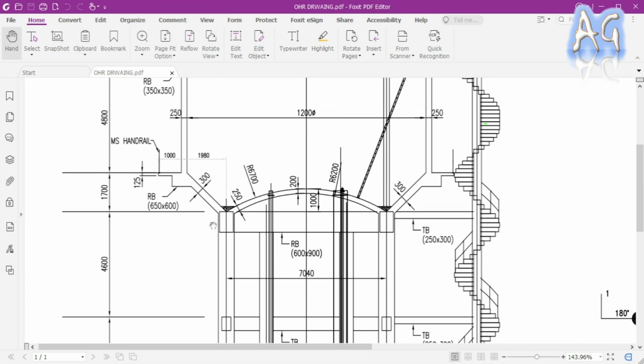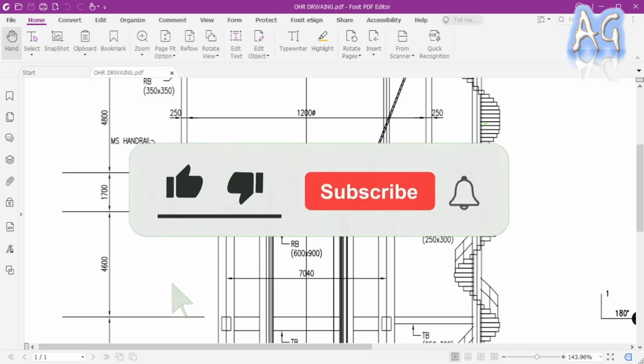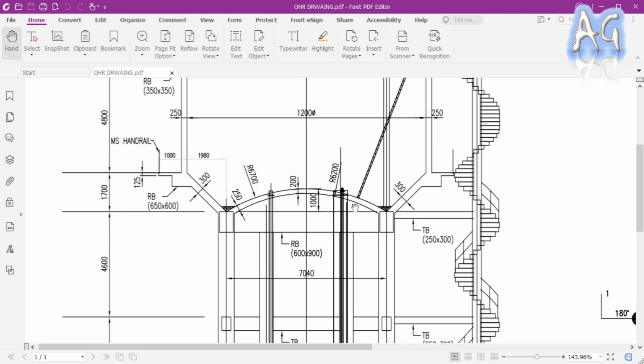So in this drawing you can see the thickness of the bottom plate is varying. Here it is 200, here it is 250. Either you can provide the average thickness or you can take the minimum thickness, because when we are designing, our design should be on the conservative side. If you consider the lowest thickness value, it means if the structure is safe at the lowest thickness value, then it's okay. So you may consider this lower thickness value, which is 200.